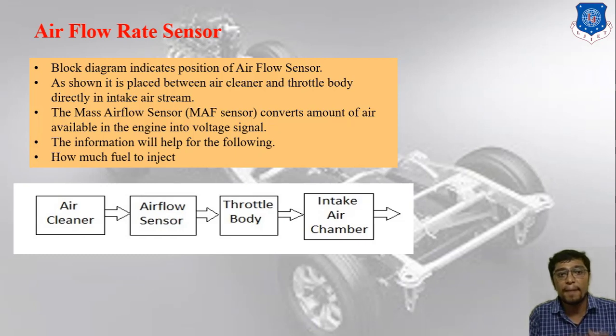Second one, that is, the mass airflow rate sensor, or you can say the MAF sensor, converts the amount of air available in the engine into a voltage signal. And third one, that is, the information will help with the following. First one, how much fuel to inject inside your chamber. And second one, it improves the engine performance, right? It also decreases the knocking. So this is the concept of the airflow rate sensor.